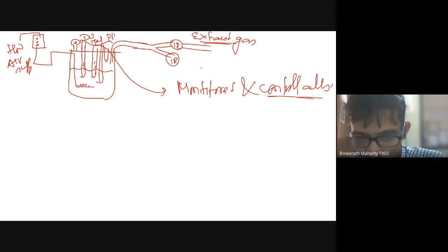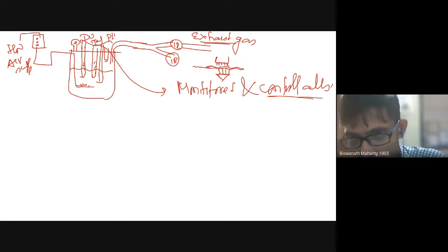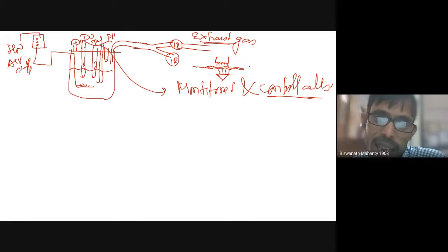Basically what is happening here is that carbon dioxide is causing a change in resistance in a filament. We can have a filament as, for example, a light source producing radiation, and we are measuring the light coming into the receiving end. If the gas is flowing through, it will deflect the light. Try to understand the principle. The light is not visible light, it is infrared light, in the case of carbon dioxide measurement particularly.